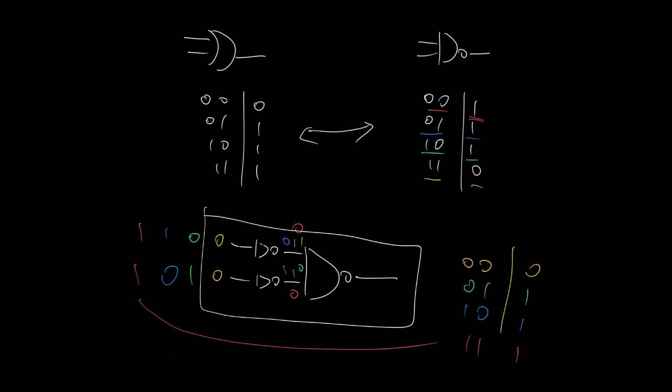And to invert the inputs, I can use a NAND gate with its inputs fused. And so therefore, this OR gate here is given by these gates here. It's a good exercise, if you so wish, to write down the truth table for this circuit, where my inputs are A, B, and because I've called this input and this input A, it receives the same signal. So if you really wanted, you can add those extra lines in there. I'll do it in a different color.